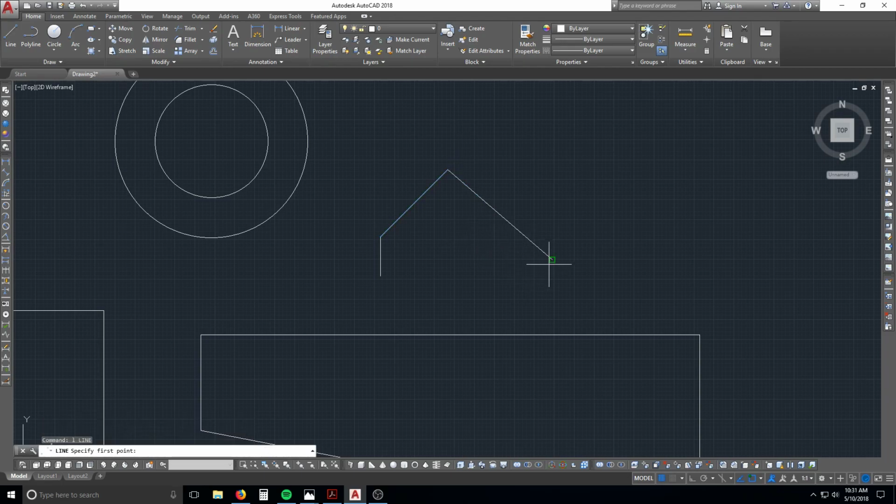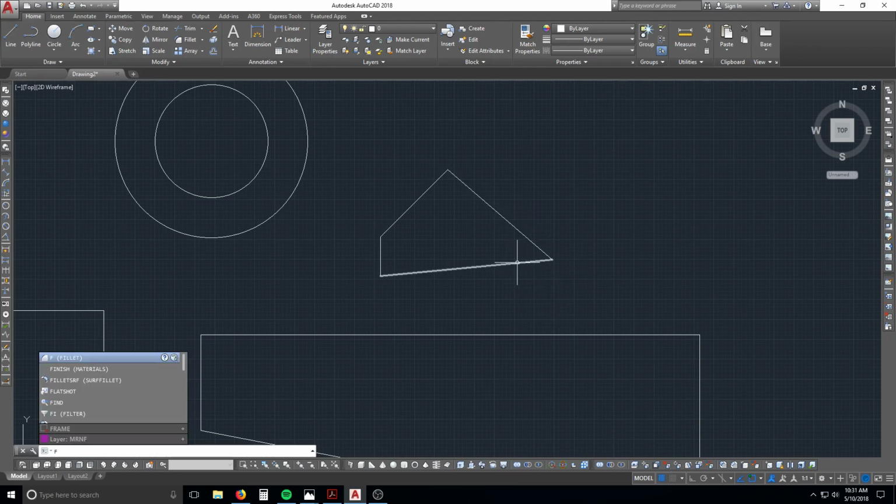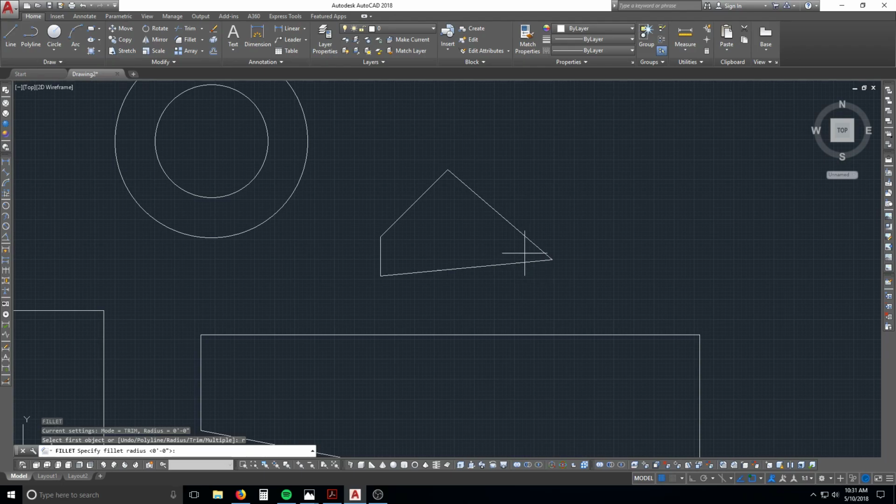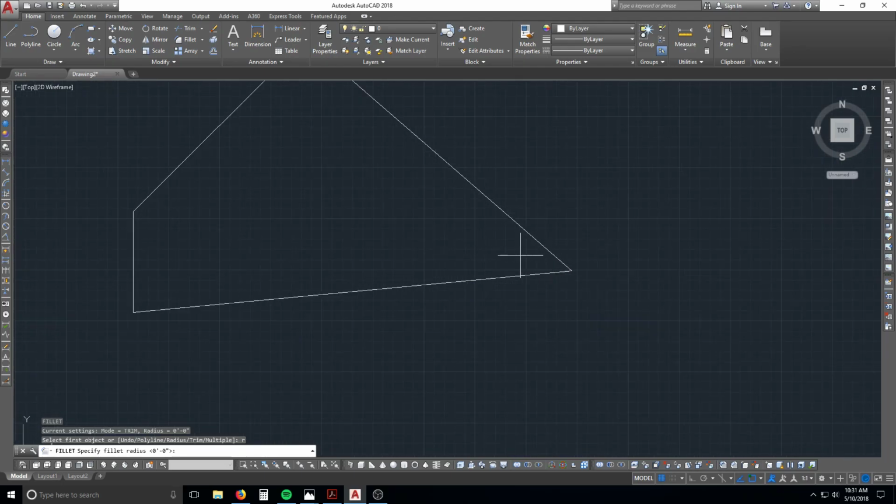And if I drew another line, L, enter, left click, enter, to get out of that. Now what if I want a rounded corner on this one? How do you do that, Brian? Well, that's easy enough. Fillet, F, enter. Now again go back to your radius, R, enter. You can eyeball it or give it a known numerical value, but I'm just going to eyeball it. I want the radius to be something like that big, just whatever. So this one, you can see what it did.